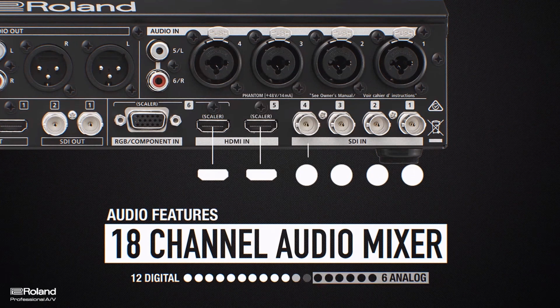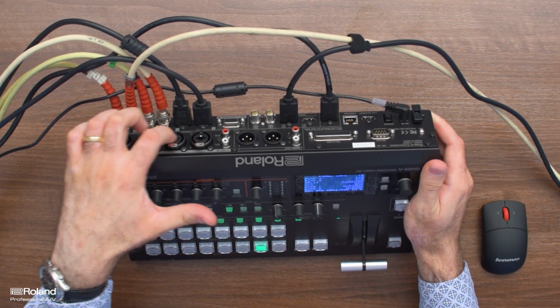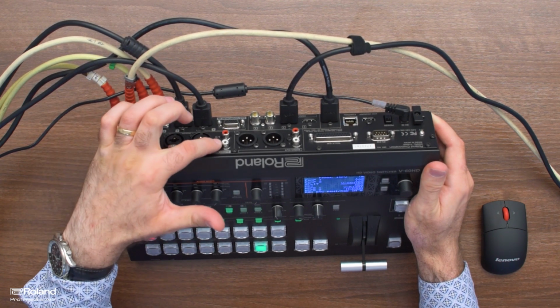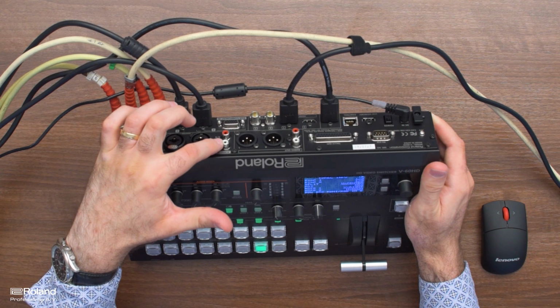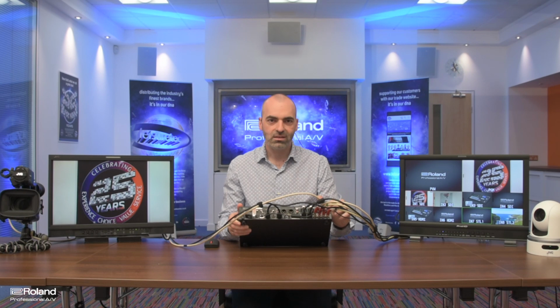The V-60HD features an 18-channel audio mixer which includes 4 XLR TRS combo jacks with 48V phantom power, RCA stereo, plus audio de-embedded from the 6 video inputs. The V-60HD powerful preamp and dynamic effects include a high-pass filter, gate, compressor, 3-band EQ, delay, and ability to select audio follows video channel so audio passes through when a specific video source is selected.